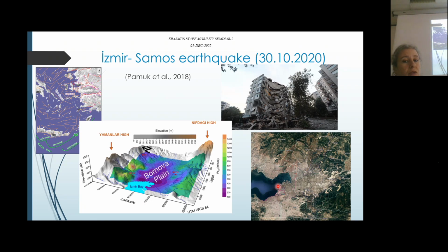And here you can see the distribution of the work that we are going to perform for the area. For each cell, we are going to obtain CPT and SPT data generally, for the rock and for the soil material at different depths. The project has already started with the drilling right now, and we are planning to have deep boreholes in order to reach the bedrock, to model the Bornova plane.